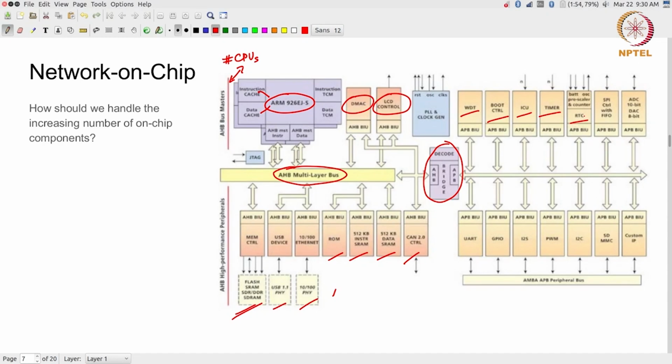What happens is, typically in a modern SOC you would have multiple of these things. You would have multiple network interfaces, GPU accelerators, graphics accelerators, accelerators that deal only with sound processing, and some other accelerator for doing the baseband processing for modem communication. By the time you add all of those together, there would be other things for error correcting codes. You add all of those together and the number of such peripherals that are talking on the bus nowadays can easily hit 20, 30, 40, 50.